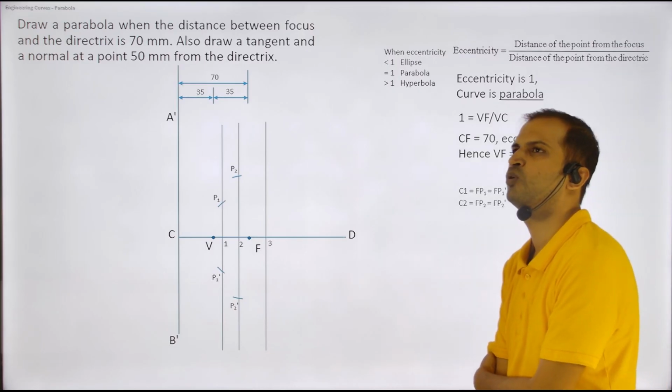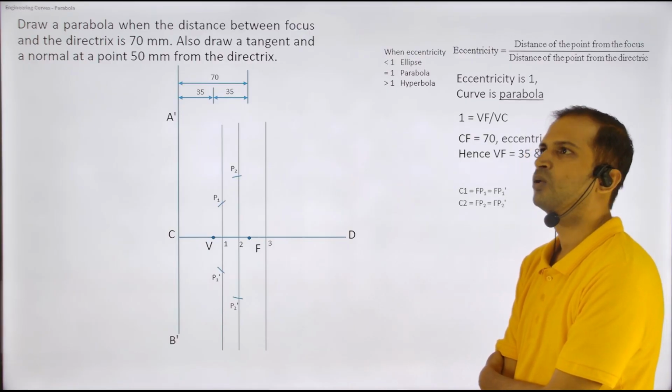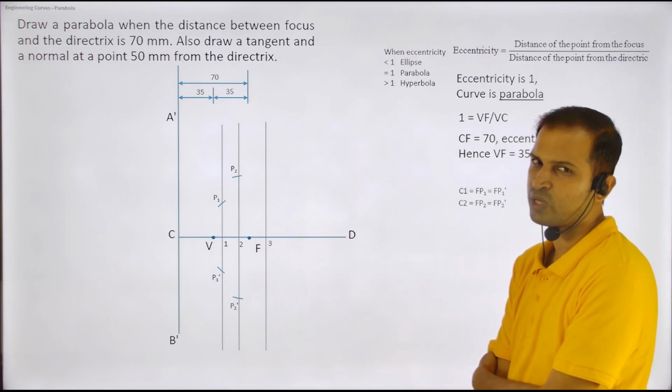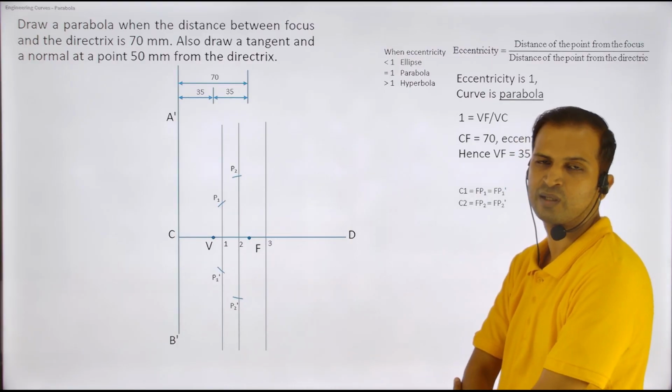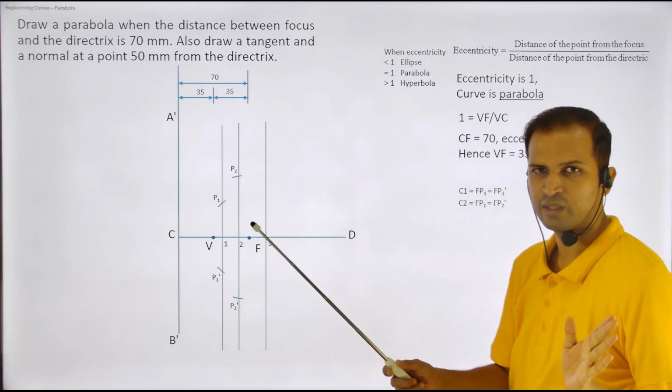See, when you are practicing, you will get an idea how far you can go with the help of the compass. If you have an old compass which is not stretching out, you can keep two types of compasses, one specifically for drawing a parabola and hyperbola with this method, a compass which can stretch far away.